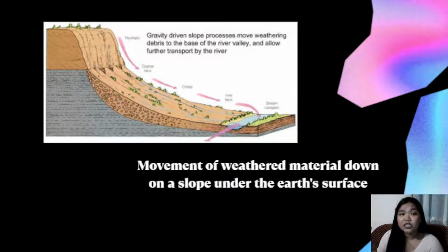A geologic formation which transmits water from one location to another in sufficient quantity for economic development is called an aquifer. The movement of water is possible because of the voids or pores in the geologic formation. Some formations conduct water back to the surface. A spring is a place where the water table reaches the ground surface. Stream channels can be in contact with an unconfined aquifer that approaches the ground surface.